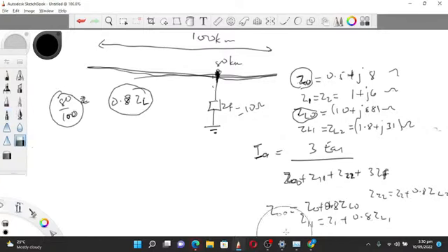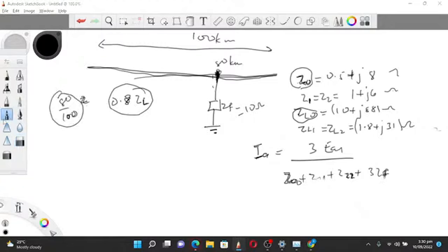Yes. And then your fault impedance was given, so very simple. You can just find your current from there. Please don't forget, the voltage they give you is a line voltage, so divide by √3. Don't let that beat you. Okay. And from there you can get your answer for the question.